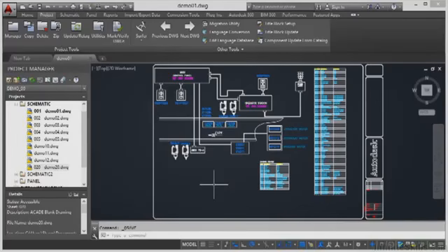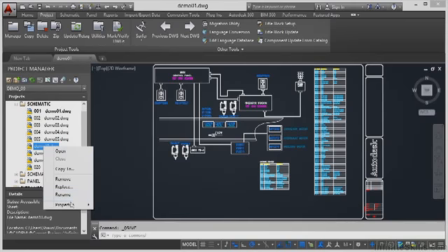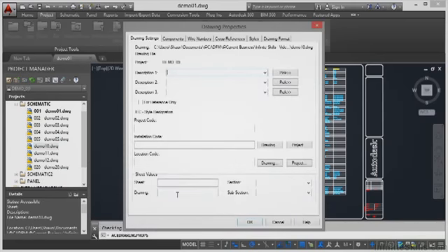You can also configure the drawing list display in AutoCAD Electrical. Now, what I've deliberately done in this particular project is I've set up drawings 001, 002, 003, 004 and 005. I've also given them an actual sheet number as well. Now, what you'll notice in the properties of any drawing is you can set up all of these properties and change the drawing list display configuration. That's this icon here. Now, what I'm going to do is I'm going to go to drawing Demo 10. I don't have to open the drawing. I just select it, right click on it, and go to properties like that, drawing properties.